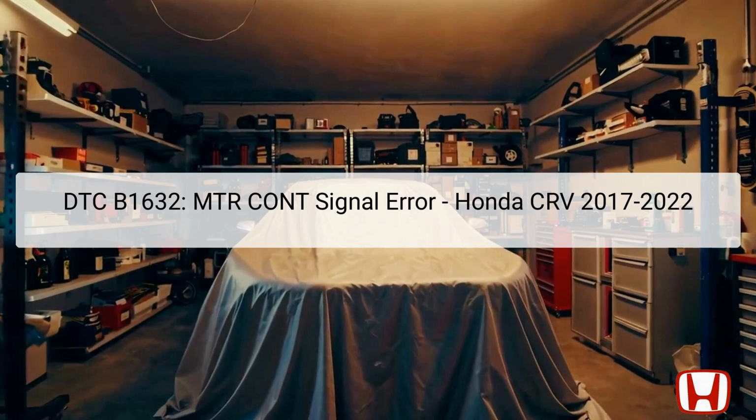The diagnostic trouble code B1632 indicates a micro-contact signal error specifically related to the keyless access control unit in Honda CRV models from 2017 to 2022. This error can affect the vehicle's ability to properly engage the electric steering lock mechanism, which is vital for vehicle security and ignition system functioning.